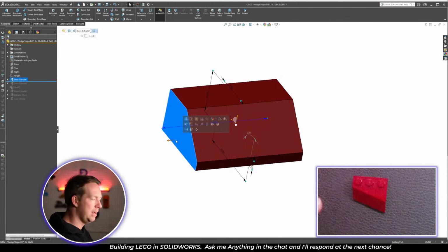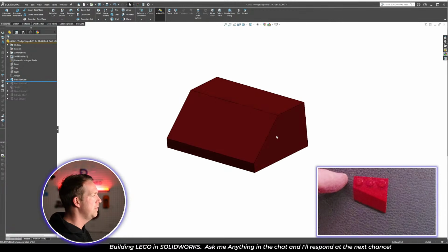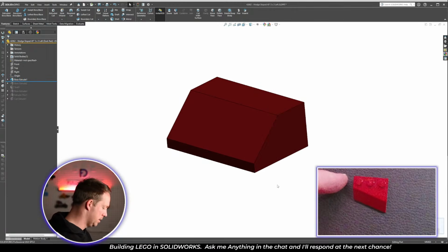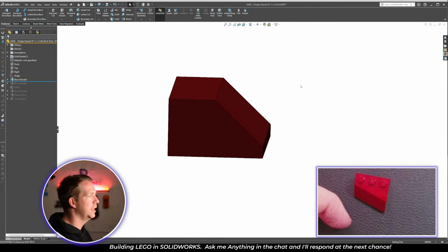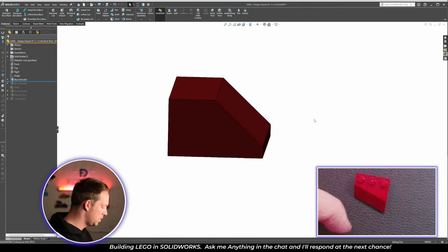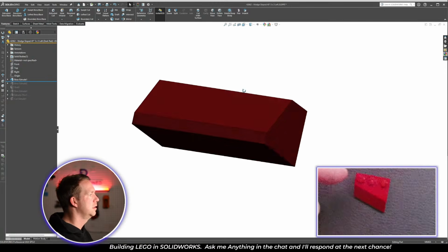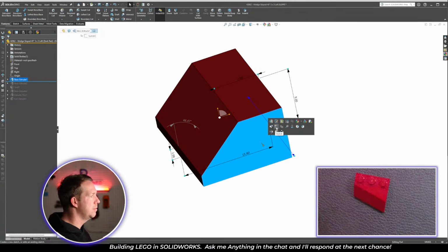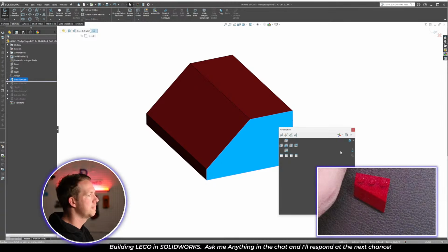And I know I've got the left side profile, so this side is correct. What I would have to do then is modify this side. Now, lofting it is definitely an option. I don't think draft is an option, because just drafting this face, it's probably going to be pretty hard to control the end dimension. So if we want to get it really accurate, we probably want to dimension this side separately. And having it here as a starting point makes that quite easy. So I'm going to use this face as a sketch plane.